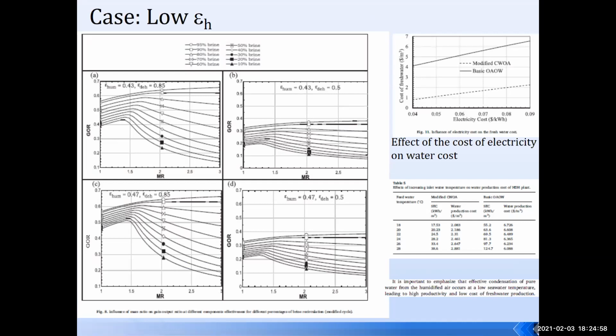These are some of the results that we got for this system. I'm not going to discuss these results now, but I can put the paper for you here on the system. And you can see here there are conditions where the system is operating with the idea of recirculation. It is associated with the effectiveness of 0.3, 0.5, 0.47. This is where you can get, especially for the humidifier, 0.43 and 0.45. This is 0.47. This is the effectiveness that is going to result in high temperature leaving the humidifier. And then you better use it instead of the flow coming from the dehumidifier.